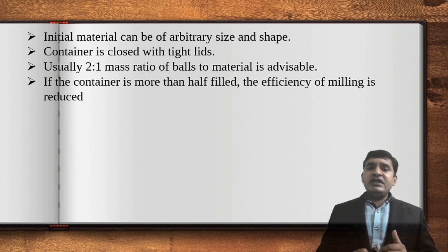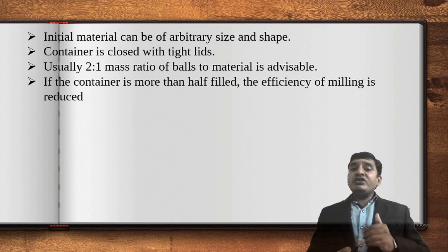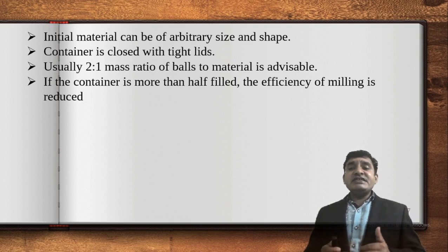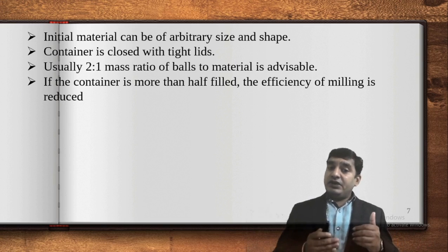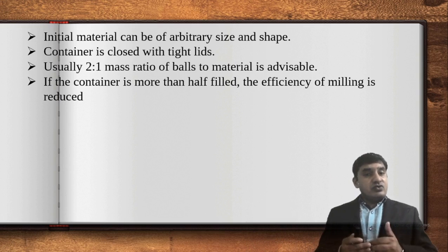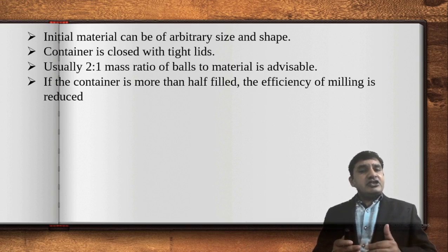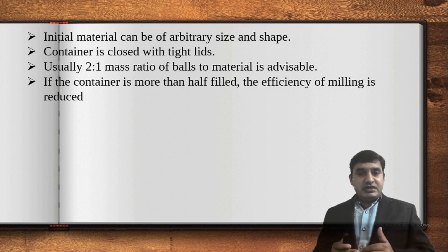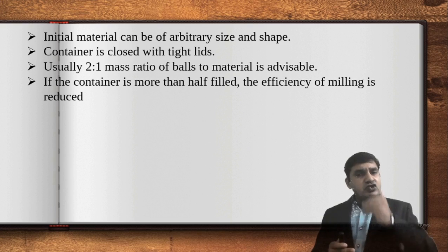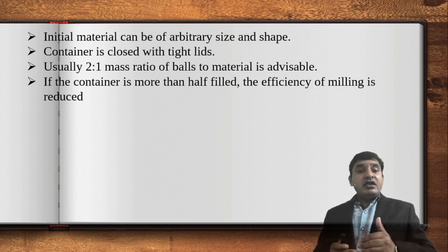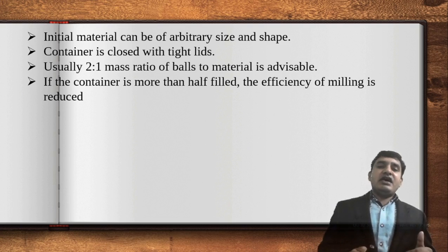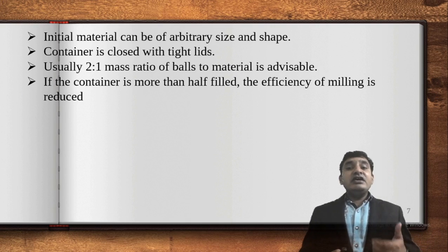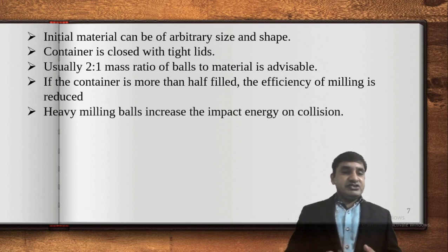If the container is more than half filled, the efficiency of milling is reduced. So the container should not be filled completely. It should be filled less than half so that the efficiency can be increased.